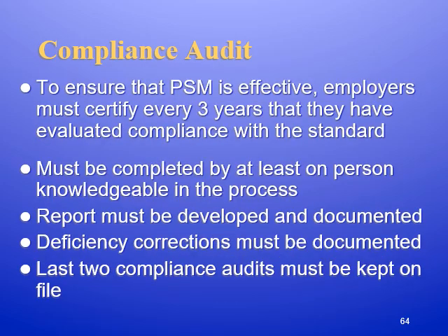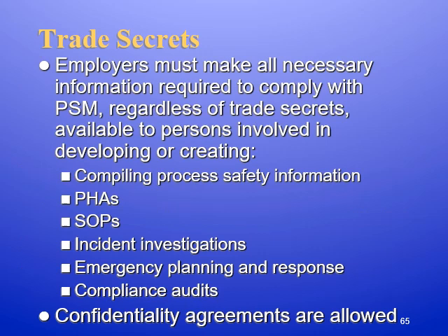And then a compliance audit to ensure that everything is going correctly. To ensure that PSM is effective, employers must certify every 3 years, just like training, that they have evaluated compliance with the standard. It must be completed by at least one person knowledgeable in the process. A report must be developed and documented. Deficiency corrections must be documented. And the last 2 compliance audits must be kept on file.